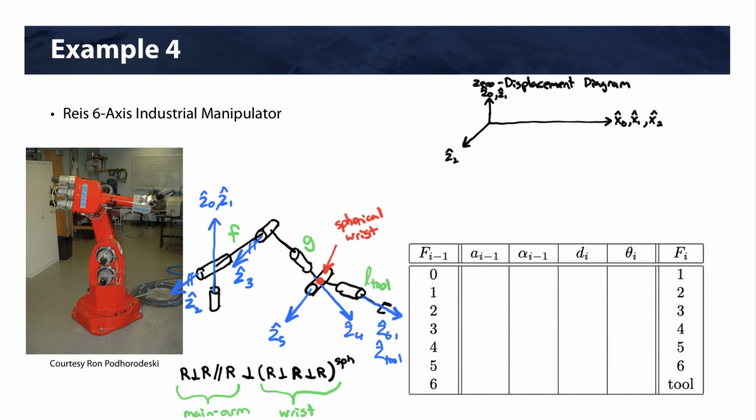Okay, so we're going to have a length F here, and we know joints 2 and 3 are parallel, so Z3 will be here, and we're going to indicate that these two are always parallel to each other, and that places X3 there. We're then going to go down to our spherical wrist, so this is going to be G. All right, and we're going to have Z4 there. We're going to have X4 here.